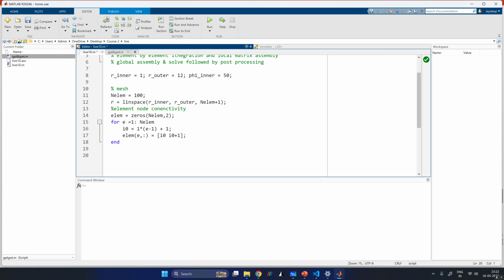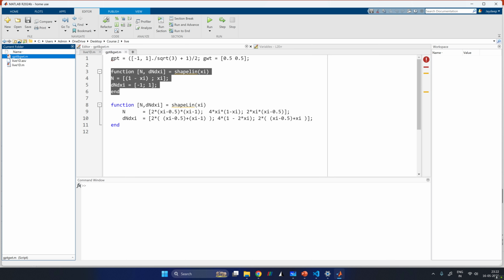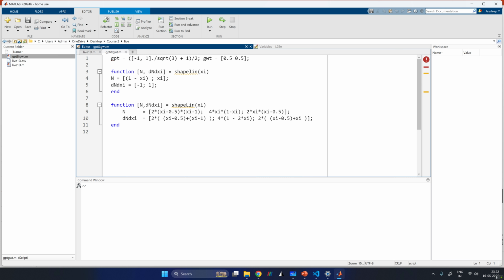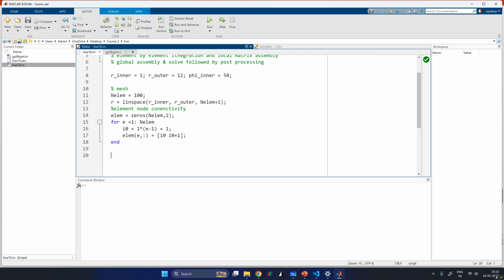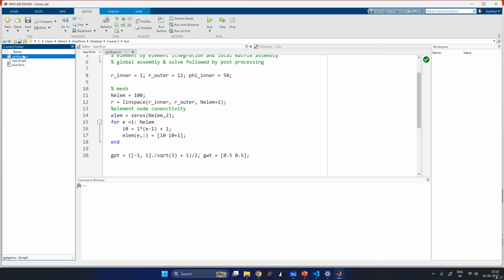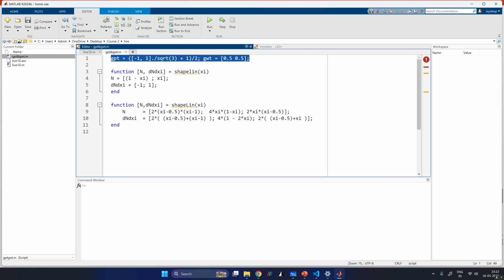So now let's go to the next step, which is pre-computation. I have just saved these Gauss points here. I have derived in the previous course the 2-point Gauss rule. If you are interested in it, you could go through it just to understand the basics. But really these values are just available on the internet. We are using shape functions and Gauss points defined from 0 to 1. So the master element is 0 to 1.